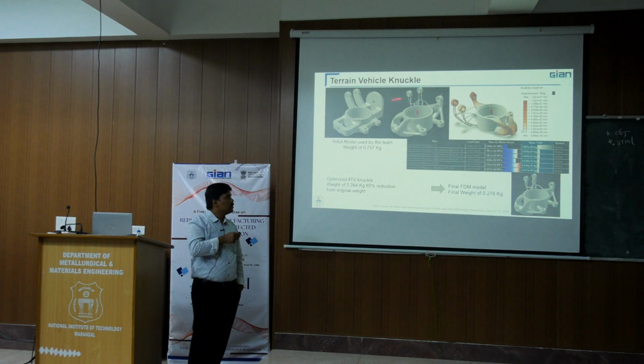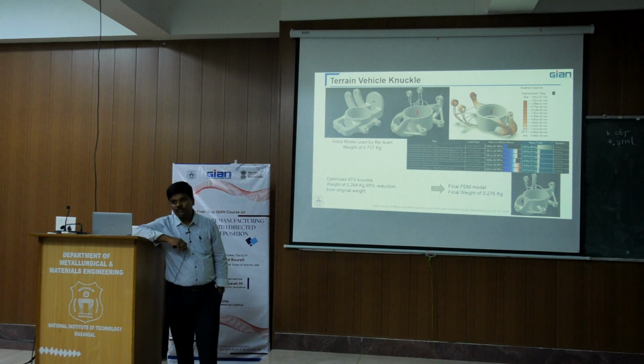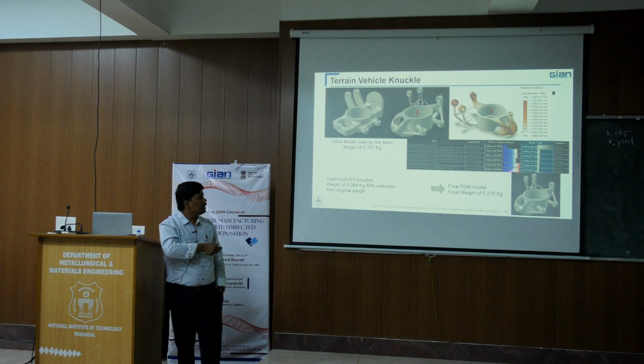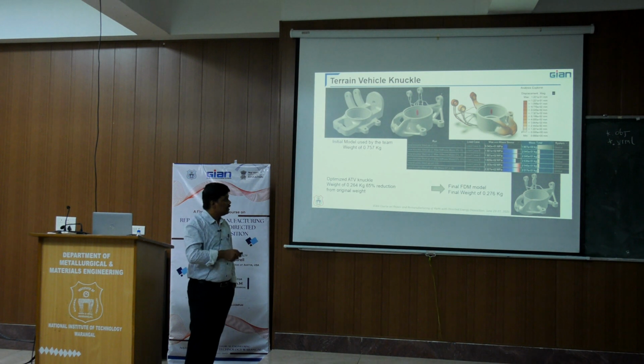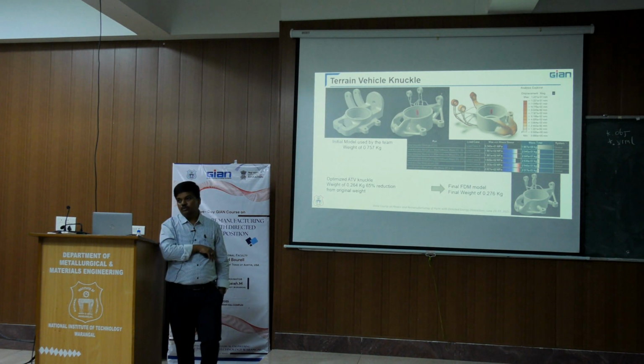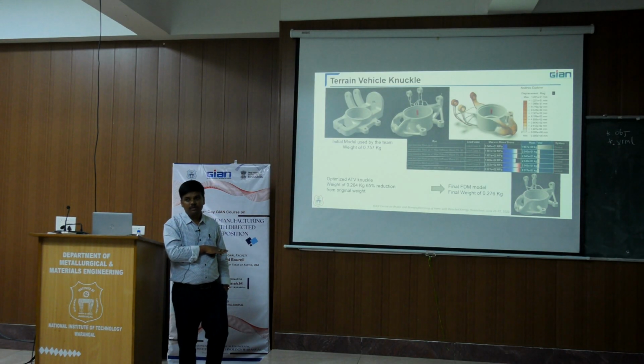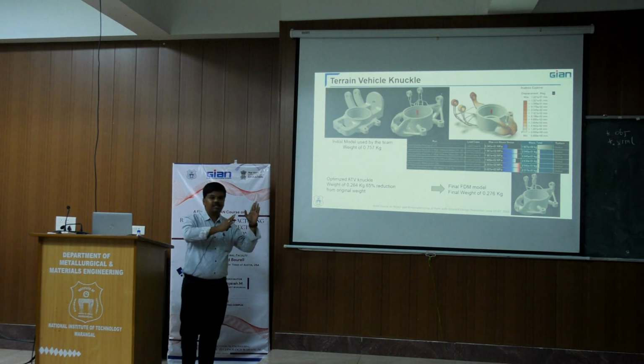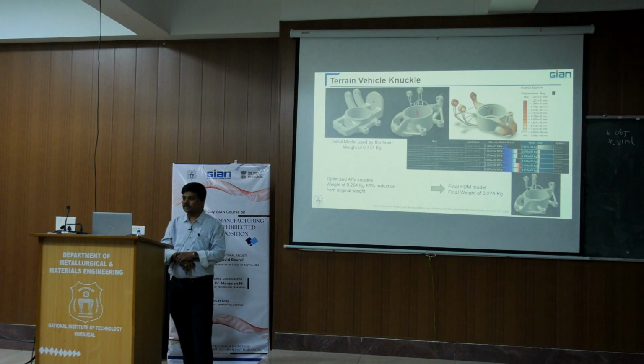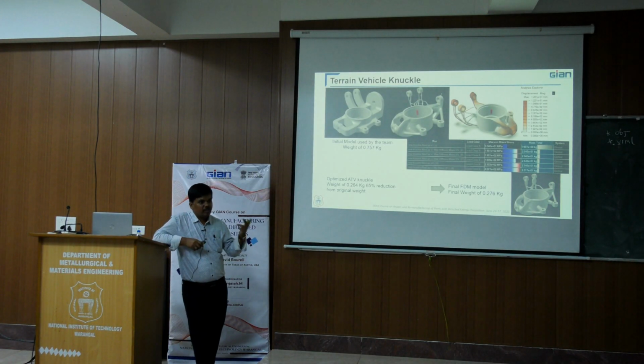We considered all the loads as well as the factor of safety. We did several iterations with FEM as well as nTop, and finally we ended up with an optimal design of 0.276 kg for the component. That means we have reduced almost 65% of the weight of the component. That is why understanding topology optimization is required.